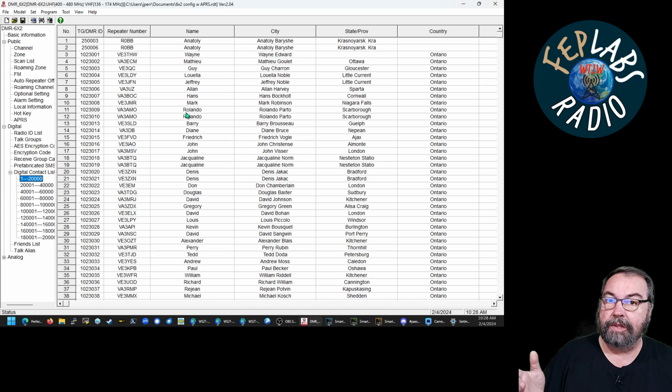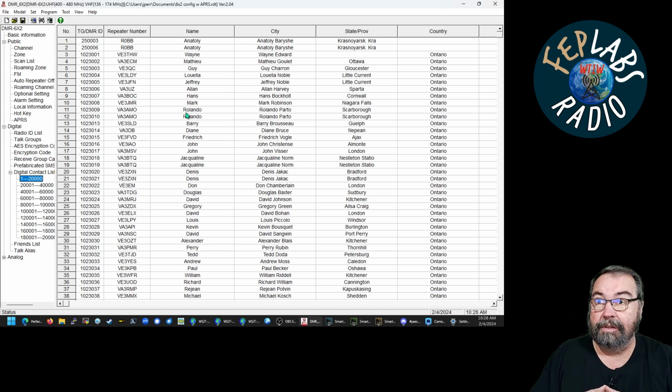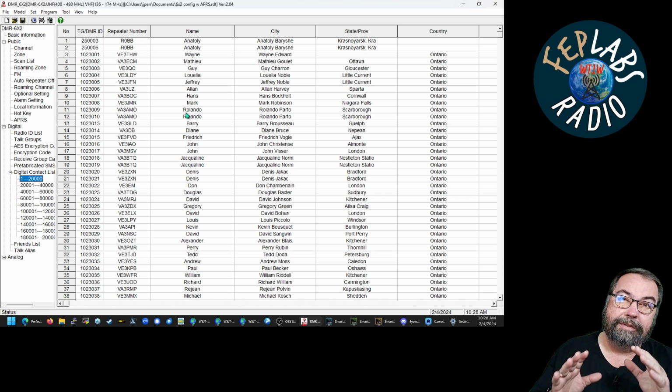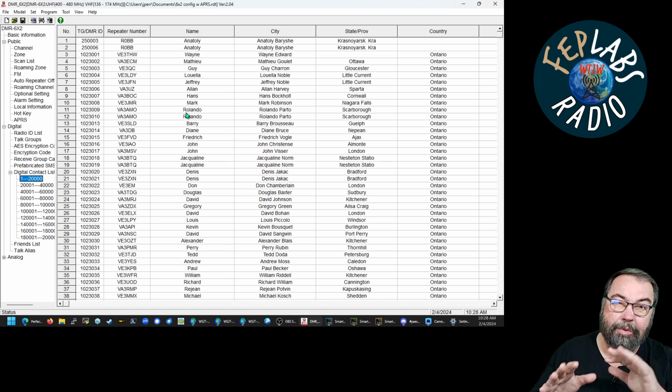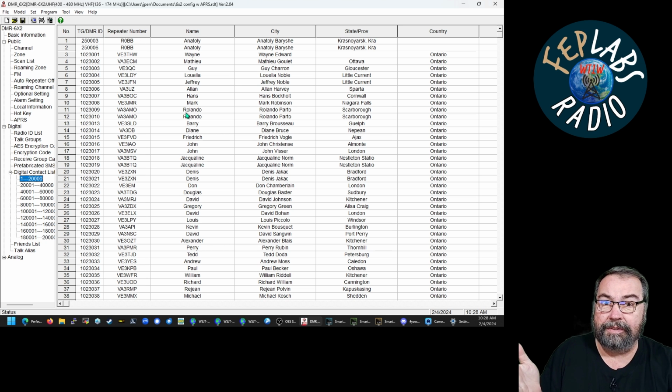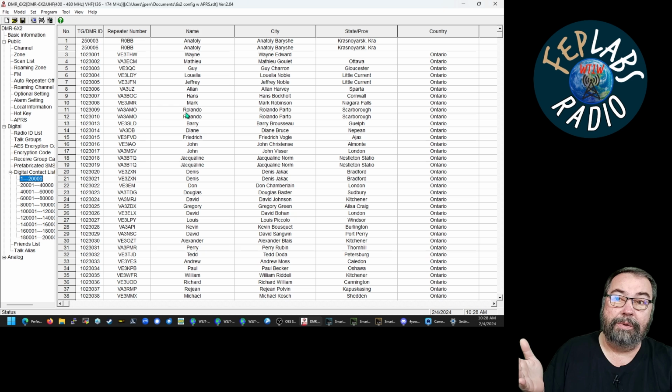There are probably some sites that let you have some functionality for free through radio vendor sites. You can pay radioid.net, I don't know, it's pretty cheap, and have access to create a custom database. Every DMR radio will hold a certain amount of contacts. The worldwide DMR database, the last time I looked, which has been probably 6 months or a year, was around 210,000, I think. A little more, a little less, give or take 20,000. This particular radio only holds 150,000 contacts, I think. So I cannot load the entire worldwide DMR ID database.